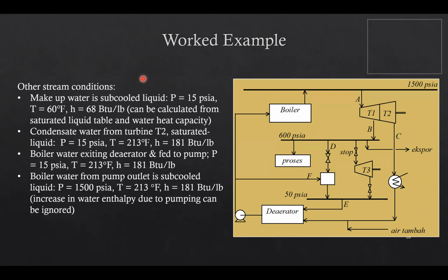Thank you, sir. Okay. This is the condition, still the data. Because we have make up water flow, and then the deaerator flow, and then boiler feed water flow, and also this one. This one is the condition after the pumping. After the deaerator, it will be pumped. The flow is separated to the desuperheater and also to the boiler. Do you have any question about this information? No, sir. Okay.